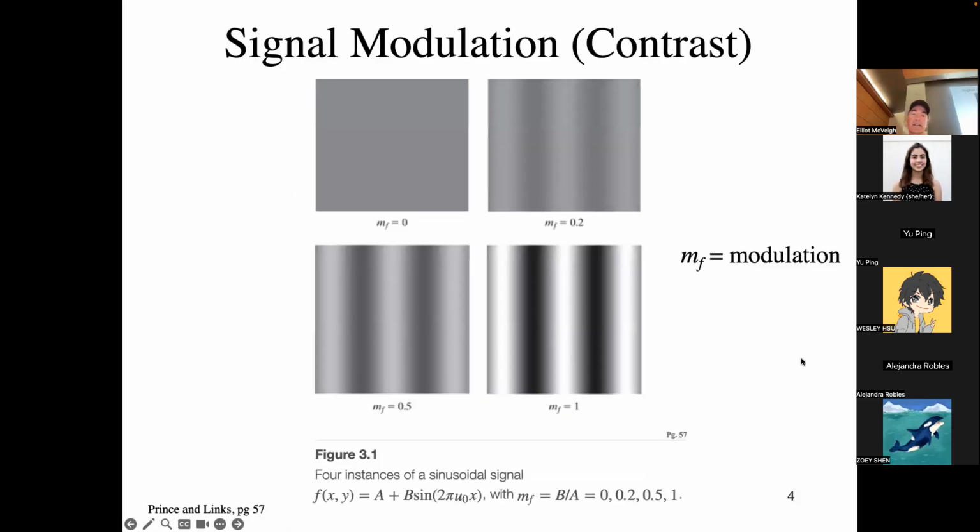One of the primary things that we're going to deal with in this course is how imaging systems behave when they're imaging a signal that is oscillating in amplitude at a specific frequency. So in imaging, a frequency is a spatial frequency. It's like, what phase of a sine wave am I in as I move along in space? So it will have cycles per meter, or radians per meter in the image. So here's a simple image that is a constant. It's got one value in the background. There's no change in the signal as a function of position.